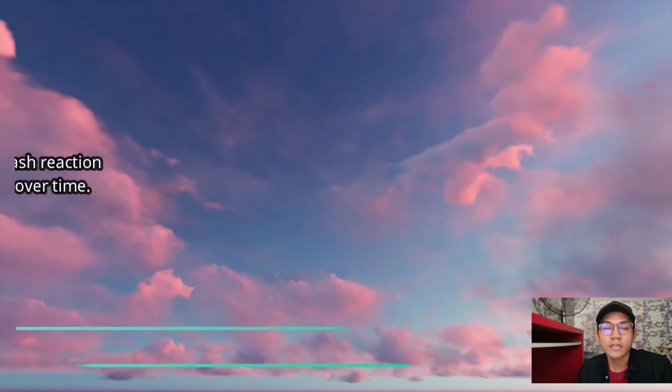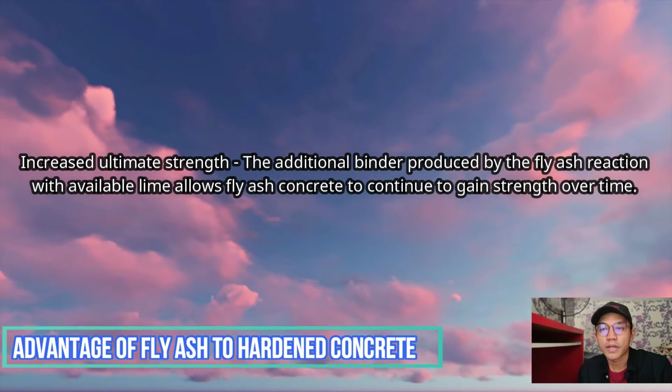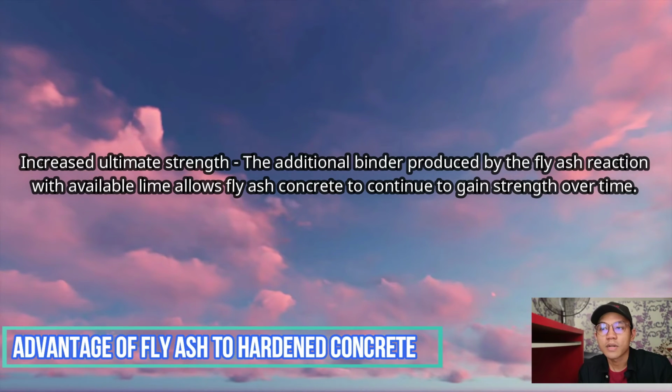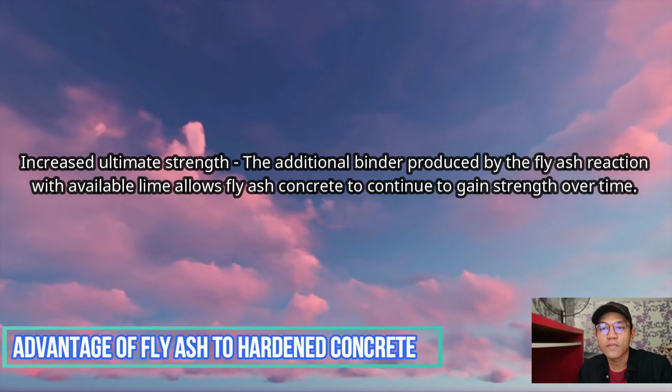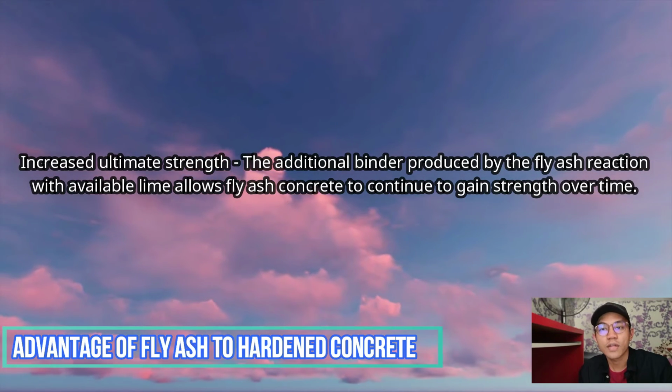Advantages of fly ash to hardened concrete. First, increased ultimate strength. The additional binder produced by the fly ash reaction with available lime allows fly ash concrete to continue to gain strength over time.